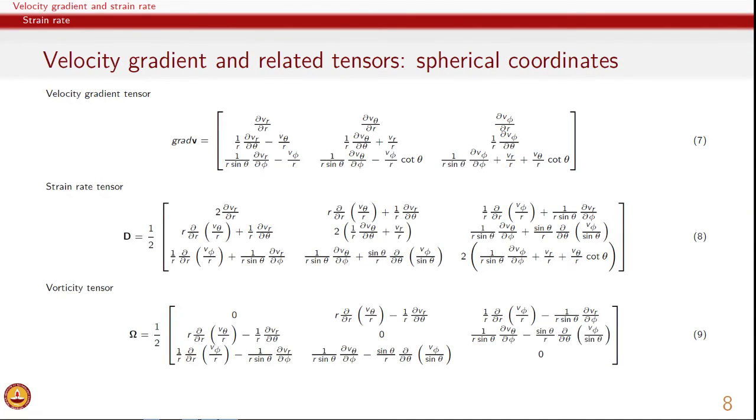During the introduction, we discussed, for example, glass fiber reinforced nylon, and in those cases, the glass fiber can also tumble. So the orientation of the glass fiber can change depending on the nature of the vorticity that is available near the glass fiber. So if we are interested in knowing the orientation of glass fibers in such a case, we should also get information about vorticity. But as far as stresses are concerned, stresses would be related to the rate of deformation, which is given by the strain rate tensor.